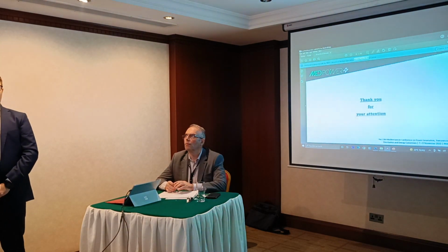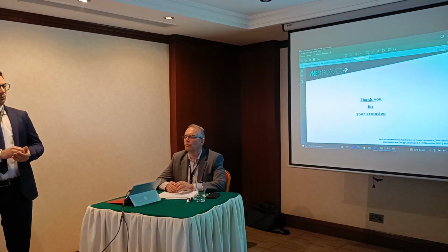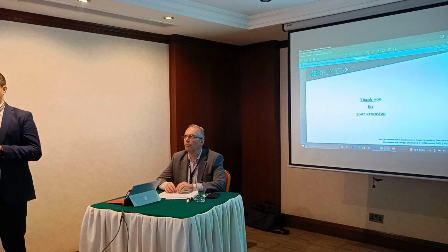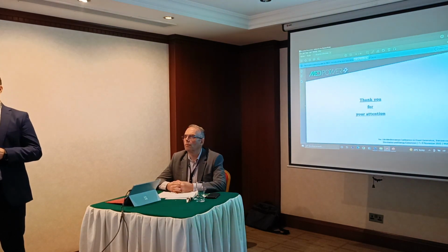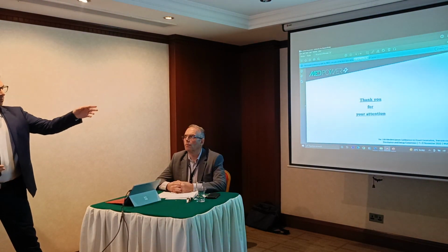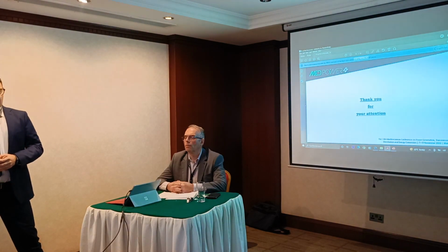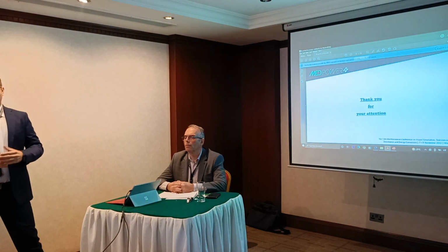We used, in fact, the PSIM software. PSIM software permits to simulate a real component by considering also the temperature behavior of the IGBT. In fact, it's possible by PSIM. It's possible to download the LTspice model of the IGBT. So it's real. In fact, the next step will be to evaluate experimentally in order to verify the model.